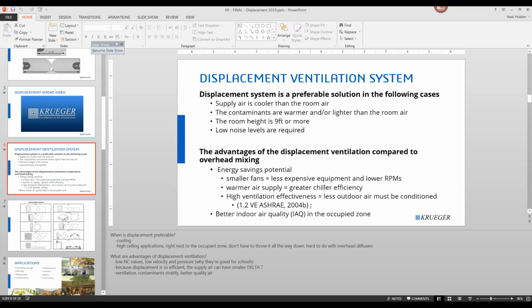A lot of radiant panels take up a lot of space in a ceiling. So if you're covering the whole ceiling with radiant panels, then it becomes less of a question of where it has to go. I think that would be specific to the application, but I don't think there are any negative ramifications of placing displacement directly next to a radiant panel.